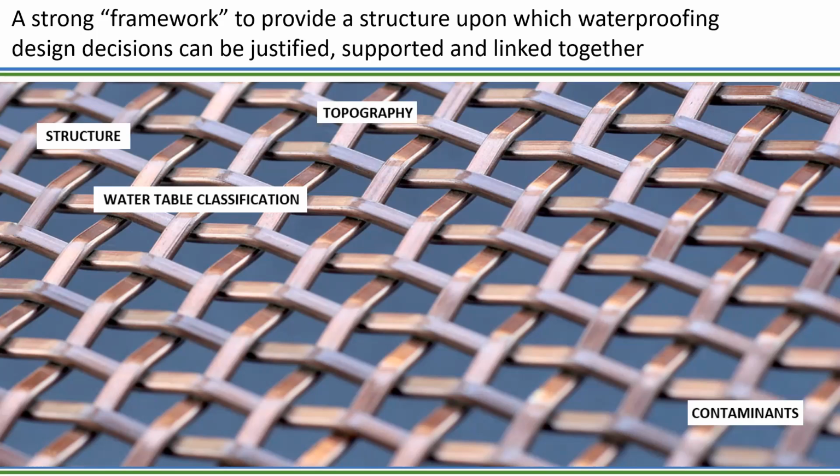Contaminants: methane, radon, CO2, VOCs, volatile organic compounds, contamination. I need to think about all that, and that is generally thrown up in the site investigation reports or the geotechnical reports, which are normally part of the planning condition of the basement. Soil gases, I've talked about.